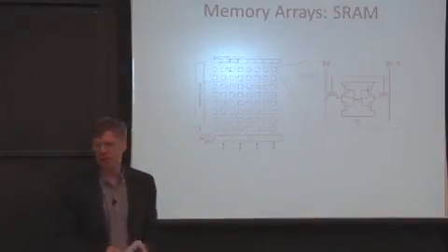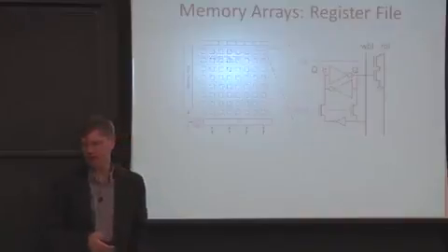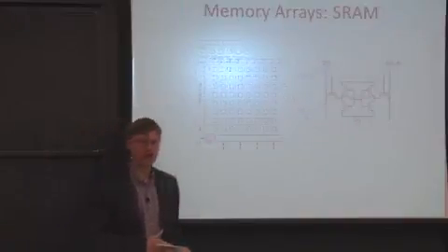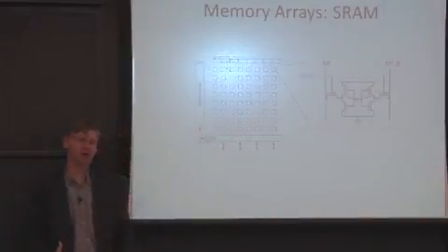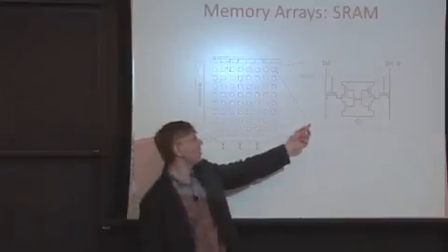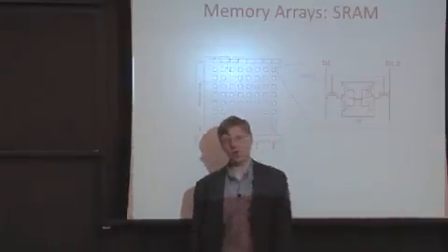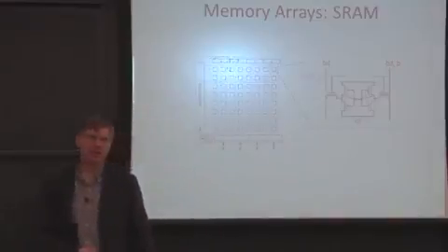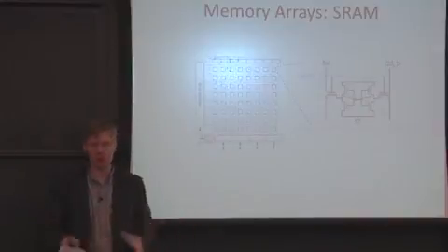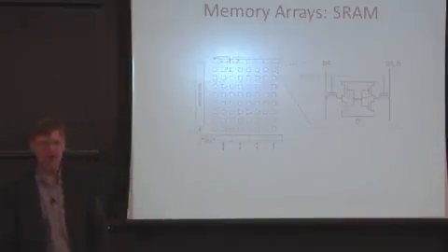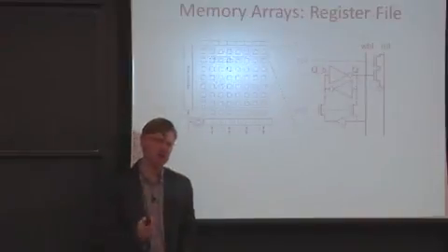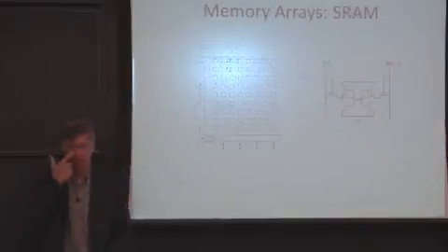And one of the differentiations I wanted to make between a register file and this SRAM here is that the register files many times are designed to be sort of multi-ported. But in this diagram here, these bit lines get reused. They're both read and write bit lines. So we've effectively built a single-ported SRAM. Having said that, people do build multi-ported SRAMs and single-ported register files, but conventionally, you build a register file when you need speed, and you need lots of ports, and you build an SRAM when you want to be more dense in your storage.